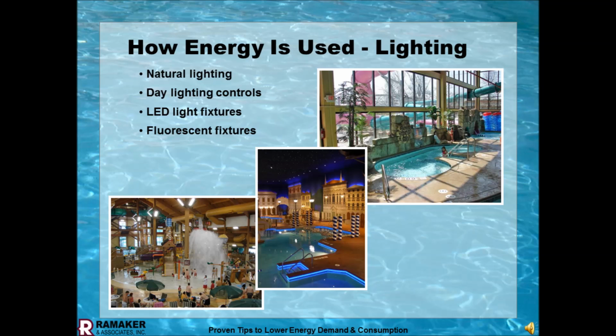Lighting, natural lighting. If it works into the building program, you're going to have some energy lost through the R factor on windows. Understand that, but be smart in your window location. Watch, or you're going to get some solar gains on it. Maybe you need to balance it out from being too much solar gain. But the end result is you can get natural lighting.